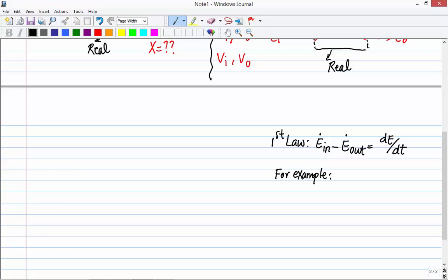we talked about mechanical energy. If you check your lecture notes, you'll find that we had this equation which says E dot mechanical equals the mass flow rate times all these energies per mass, which was pressure divided by density plus V squared, here V is the velocity, divided by 2 plus the potential energy due to gravity, so gz, right? So in this way we solved a couple of examples, right?